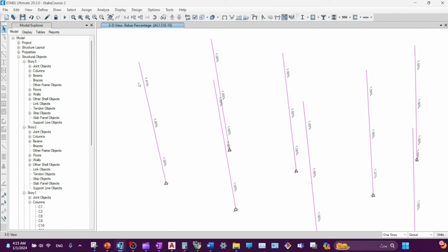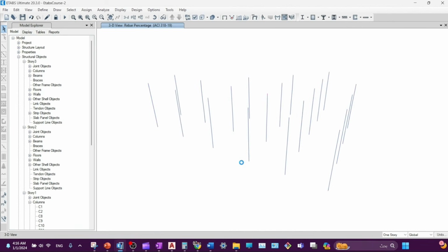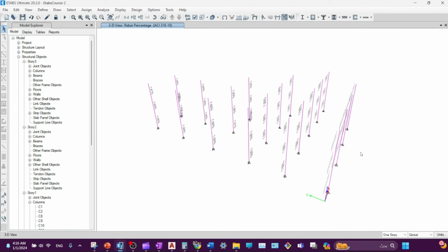So you may round it to 25, or the best solution is to increase the bar size. So assume it is 25 or 20 millimeter bars, and compute the area of steel, and you can distribute them such that the distance between bars is not larger than 150 millimeters, and if so, you need to add the middle stirrups according to the ACI code. You make a unique detail for this column from the ground floor to the top floor, and other columns will have the same detail except this one.